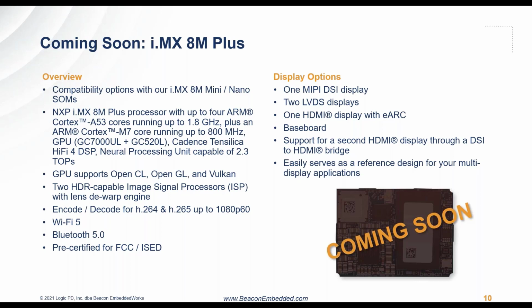Our SOM will then be upgraded; we'll include Wi-Fi 5 and we'll have an upgrade to Bluetooth 5. And once again, it will be pre-certified. One of the unique things on the 8M Plus versus the Mini and Nano, especially for those of you that are doing GUI development, is that there's a lot of display options on the 8M Plus. There's MIPI DSI display support, 2 LVDS displays, support for HDMI with eARC.